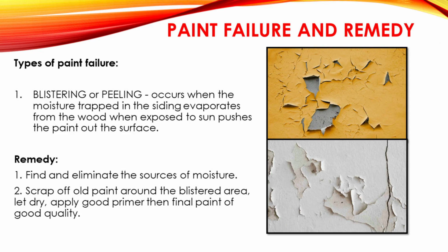Now I am going to talk about paint failures and the things that you can do to overcome this. So the excess moisture, flat grained wood, high porosity in paint, and applying a new paint coat without proper preparation of the old surface can all lead to early paint failure. The most common cause of premature paint failure on wood is moisture. Paint on the outside walls of the houses is subject to wetting from rain and dew. There are 10 different types of paint failure.